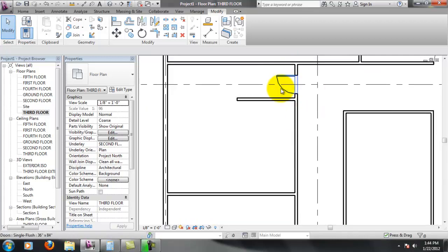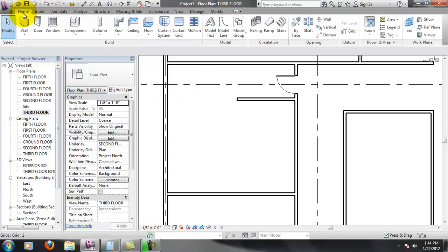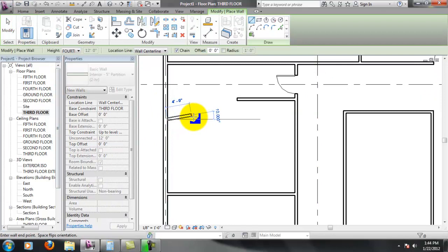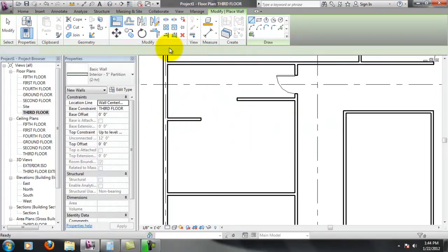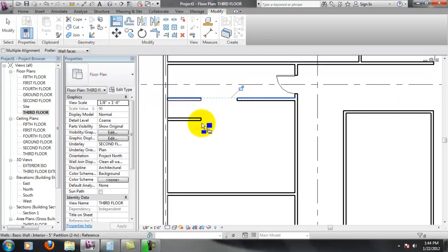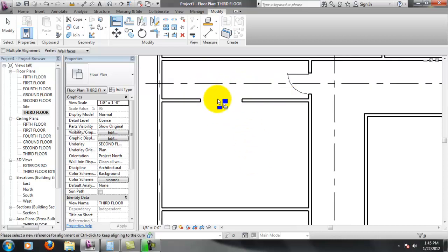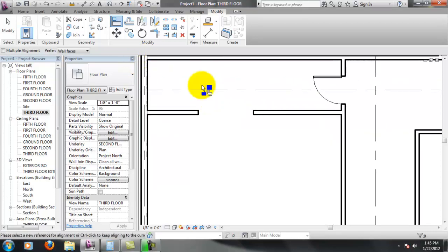Okay, so now I have the door coming in here, and sometimes you might see even a wall over here on this side. So I'm going to go ahead and draw a wall. And to show you more use of the Align tool, I'm just going to drop it in here with no certain space. And I'm going to use my Align tool again to align this space to this space. And I'll lock that. When I lock that, what that means is if I move either one of these walls, both of them will move. So no matter what I do, these walls remain perpendicular. And that's kind of what I want to do. I want to make sure that I lock walls together when they need to be.